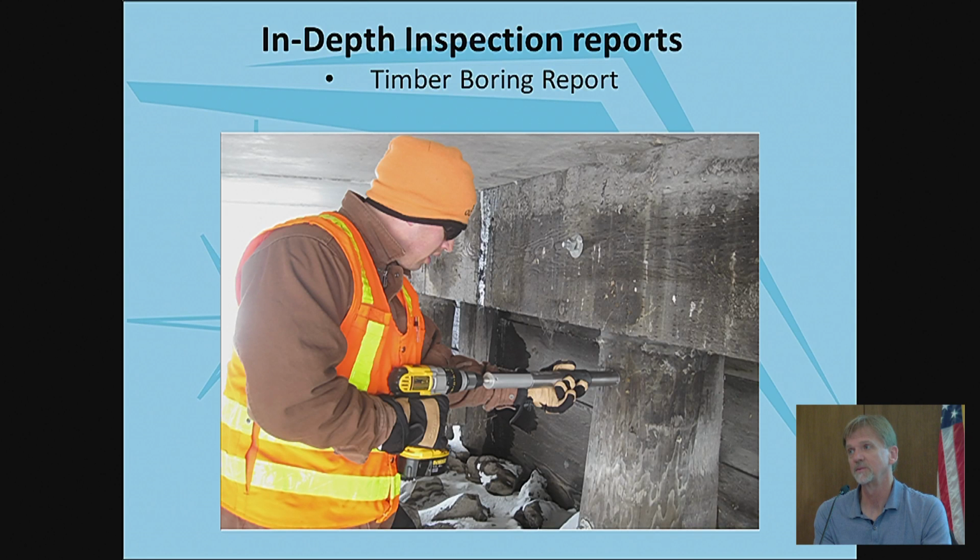And then the good old method is using a 3-pound hammer to sound the timber. I worked with a gentleman who could tell within 1 inch how much rot was in that member, just by sound, feel and rebound from the hammer. We require all of our inspectors to sound 100% of the timber members, and when it's time to bore the entire bridge, or if they find an indication in that member, then they need to drill it. We've even gone to the point of requiring a resistograph, because it just gives you the results, and there's really no lie about it. It shows you what's in that member.